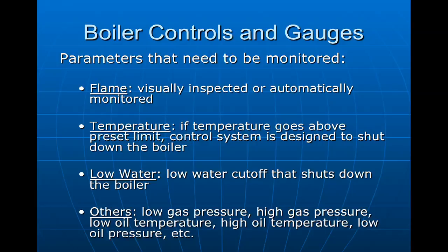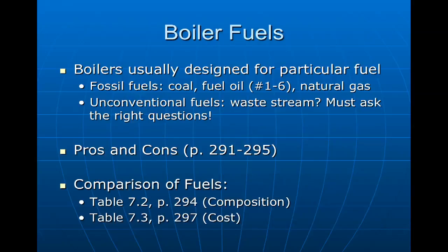Something that's not listed here is the outside temperature. What's the temperature outside? The reason we need to know that is to know how much pressure is being exerted on the building. If it's 20 below zero out, we know that we're going to want this boiler performing quite strongly. If it's not 20 below, if it's 50 degrees out like it is today, then the boiler may still have to run, but it may not have to run as hard. And so we can temper that as an energy savings measure.